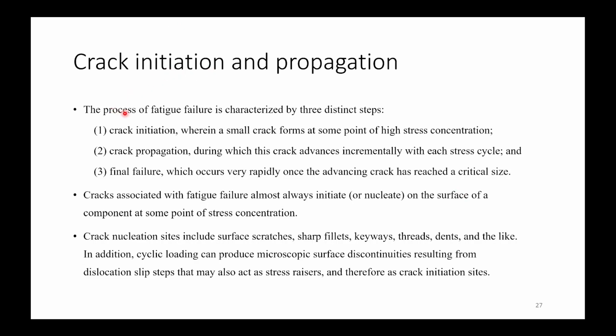Now similarly, the process of fatigue failure is characterized by 3 distinct steps. So it is told again. In case of crack initiation, a small crack forms at some point of high stress concentration.